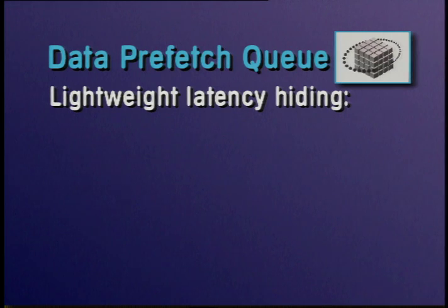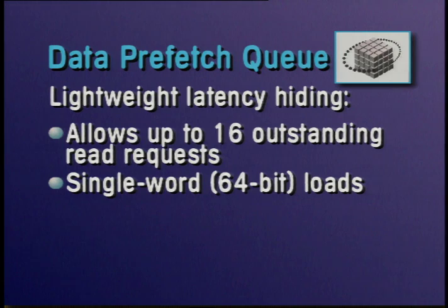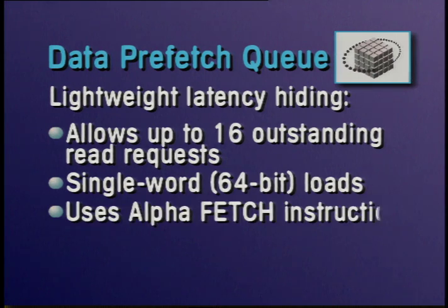We can't have the processor stalled waiting for remote references, so in T3D we've extended the memory pipeline externally by adding a latency hiding mechanism called the prefetch queue. The prefetch queue is a first-in, first-out memory, 16 64-bit words deep, that is used as the temporary destination of remote loads. Prefetches are initiated